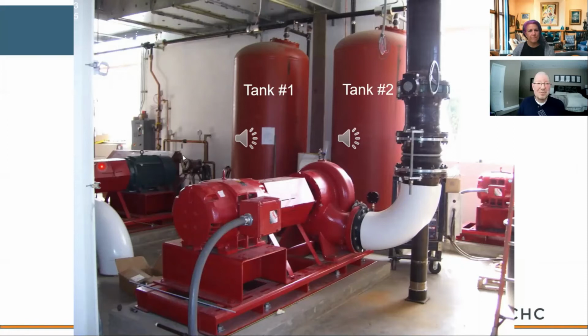Now, let's talk this one through. We've been talking about boilers all day long, or at least this afternoon. I'm throwing a wrench at you. This is a chiller, and the chiller's running. If the chiller's running, it means we're coming back from the system at 60 degrees and we're sending 40 or 45 out, okay? We're actually contracting water, not expanding water. So we're going to expect no expansion in these tanks. The only time we have expansion in a chilled water system is when the chiller's shut off and the system heats up to ambient conditions, which might be 90 or 100 degrees on a summer day, okay?